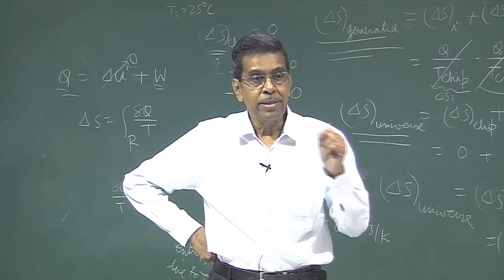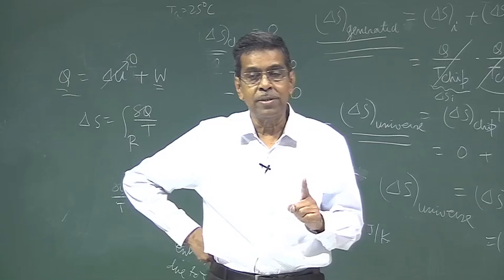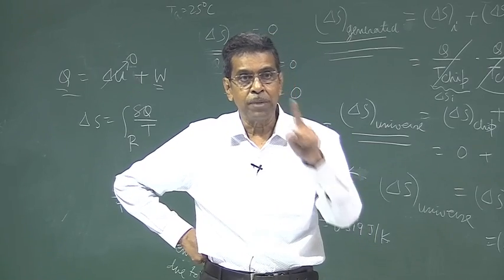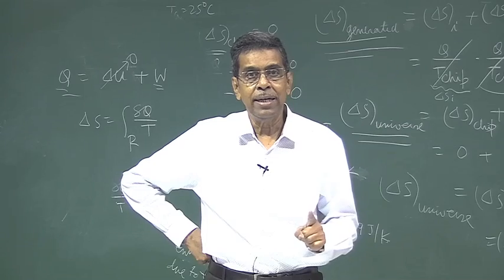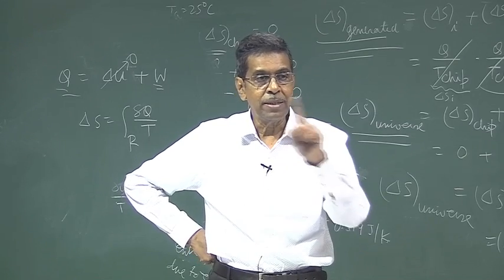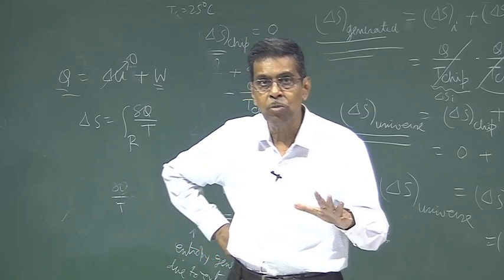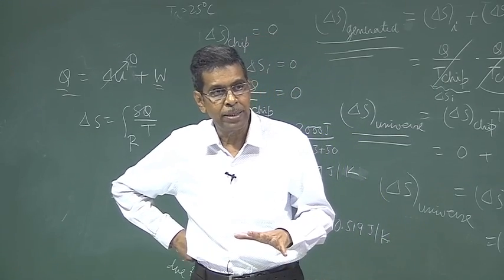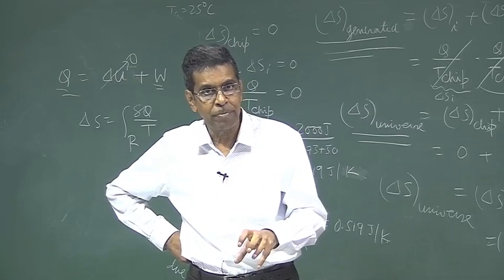This is the Clausius inequality. The cyclic integral of delta Q by T is 0 if T is the temperature of the working system operating in the cycle, then this is an endo-reversible cycle. That means internal irreversibility is 0. So in that case, the cyclic integral of delta Q by T equals 0, where T is the working system temperature.